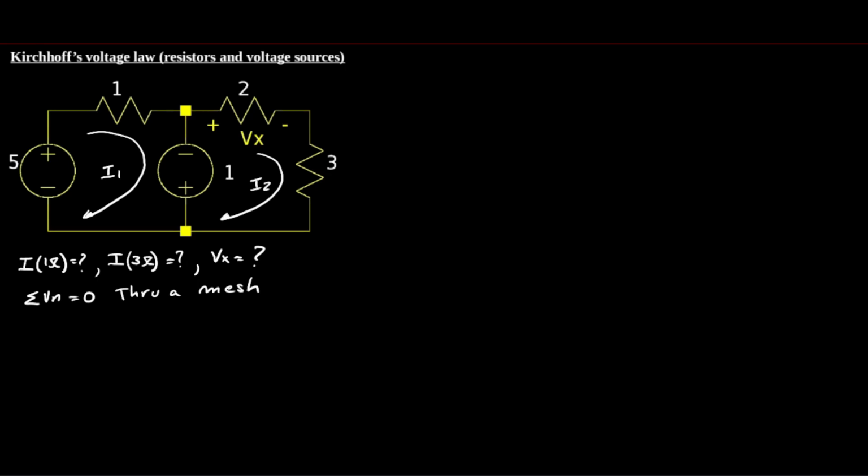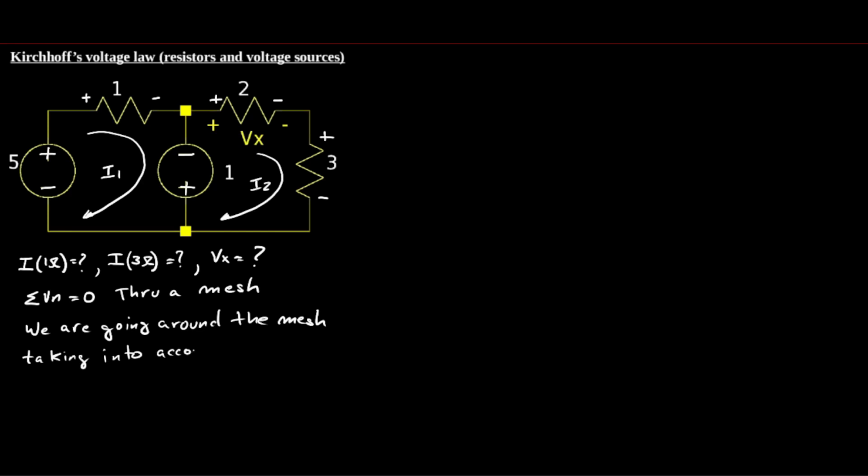So to do this, first of all, as I did before, I draw a current in a mesh the way I want. In this case, I want clockwise, and on the second mesh, I draw a current the way I desire. In this case, clockwise as well. Once I draw these currents, I have to look at the mesh on the left. Taking into account the path of this current, I find a voltage rise due to the voltage source, and then due to this current, I find that I get a voltage drop across 1 ohm resistor as I drew it in the upper side of the circuit.